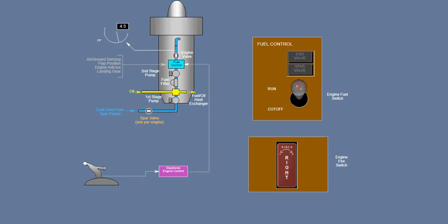The EEC sets power and provides engine limit protection, like an engine governor. Since the EEC actually sets the power, a failure of an EEC will cause the engine to fail. For reliability reasons, redundancy is built into the EECs.